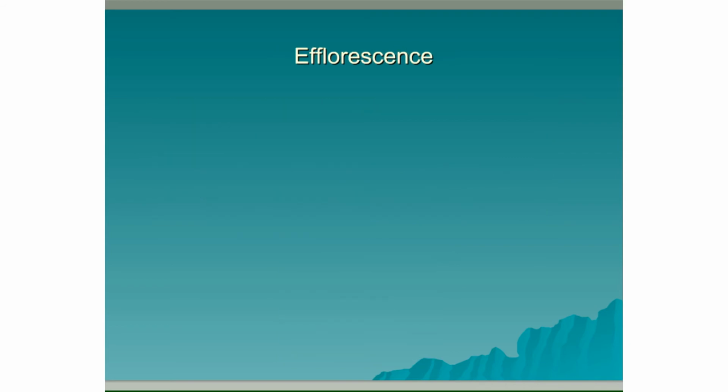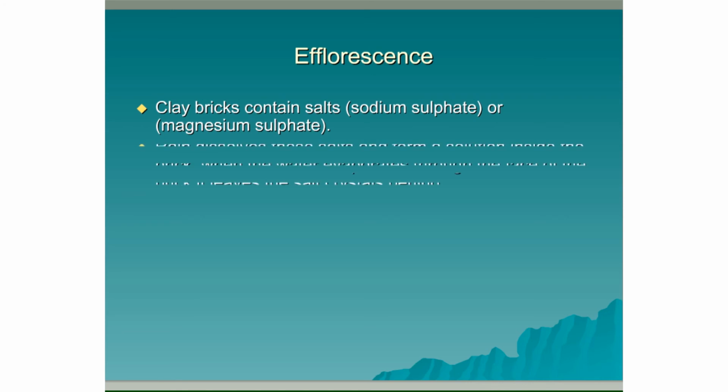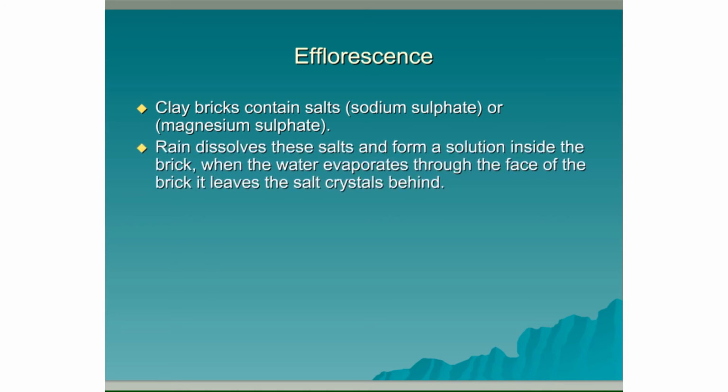Efflorescence. Clay bricks contain salts, for example sodium sulfate or magnesium sulfate. Rain dissolves these salts and forms a solution inside the brick. When the water evaporates through the face of the brick, it leaves the salt crystals behind.